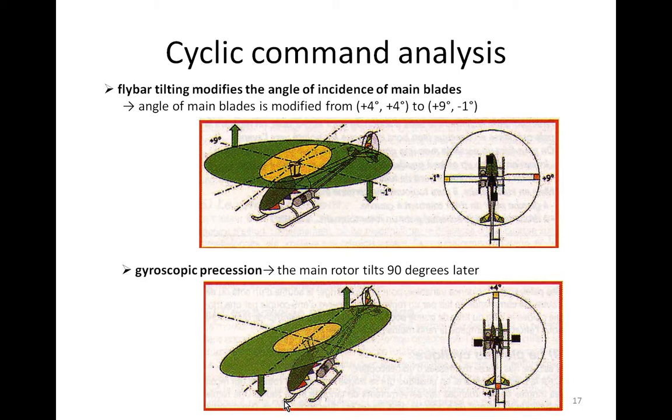So, to summarize, we just need to tilt the swash plate in the direction we want to go, and the washout manages the 90 degrees shifting. The pilot doesn't have to think about this. Just one note: on flybarless helicopters, the shifting is done electronically.